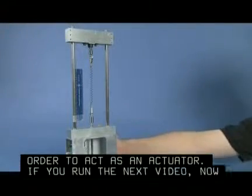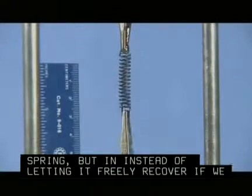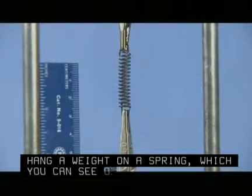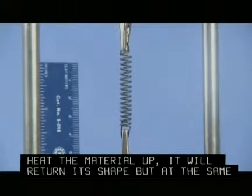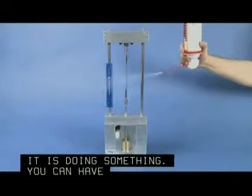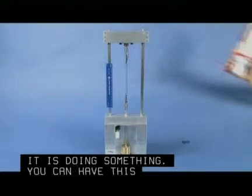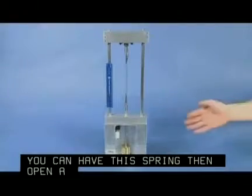Instead of just letting it freely recover, if we hang a weight on the spring, which you can see on the bottom, and you heat the material up, it'll return its shape, but at the same time now it's pulling a weight, so it's doing something. You can have this spring then open a latch, move something, and then as you cool it back down, the weight de-twins the material and pulls back the spring.